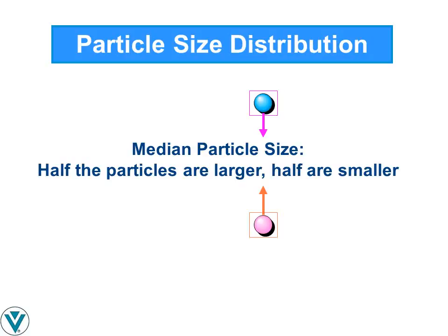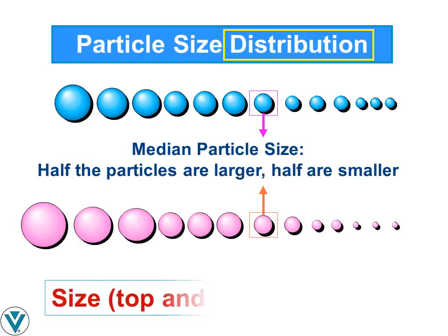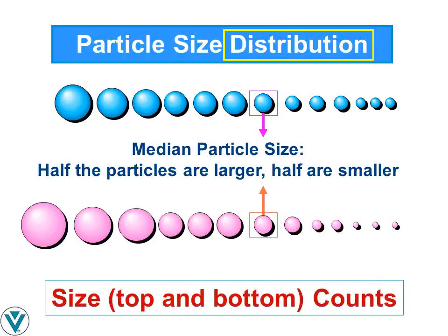For any given method of particle size analysis, particle size distribution data is somewhat useful for comparing the relative fineness of samples with similar particle shapes. However, particle size distribution rather than the commonly reported median ESD must be compared. The median indicates only that half the particles will have a larger ESD and half a smaller one. It says nothing about the size of the largest or the smallest particles, which can have a significant effect on filler performance. Neither the median ESD nor a particle size distribution can provide truly comparable results for two minerals with distinctly different shapes, such as calcium carbonate and acicular wollastonite.